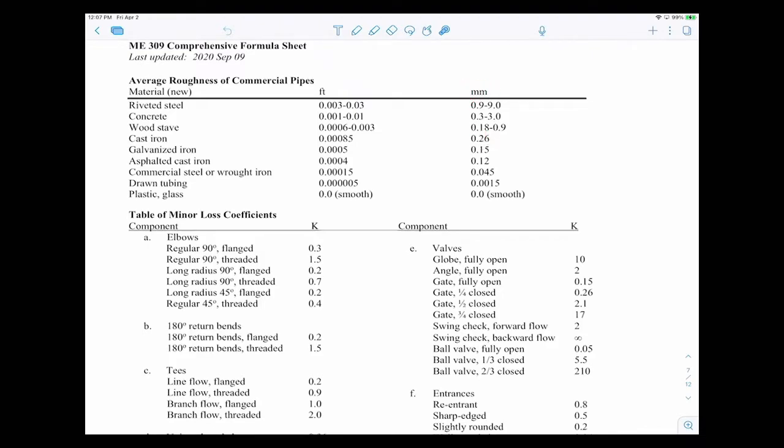Now, keep in mind that these are all just very approximate values. We're doing calculations by hand here. I'm sure there's a wide range of roughnesses for cast iron, depending on how old it is and stuff like that. Here it says it's new material, but depending on how it's manufactured, you'll get a wide range. So treat these values as just ballpark values. They're not the exact value. If you really needed an exact value, you would actually have to go out in the lab and measure the exact value for that pipe. Did you make that table? This table came from Frank White's fluid mechanics textbook, I believe. Yeah, these tables have been pulled from elsewhere.